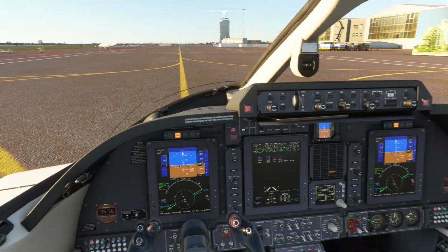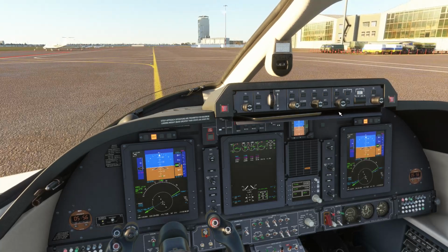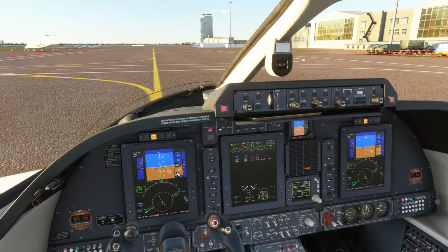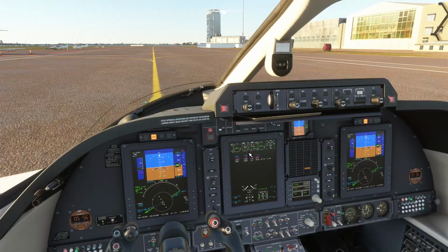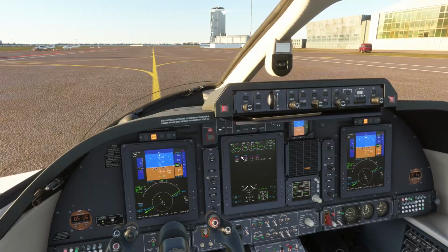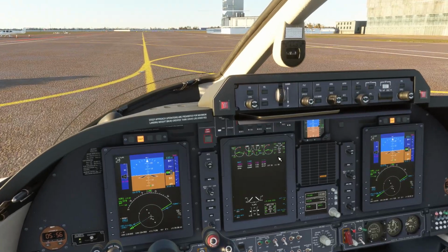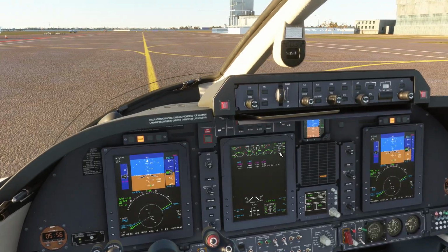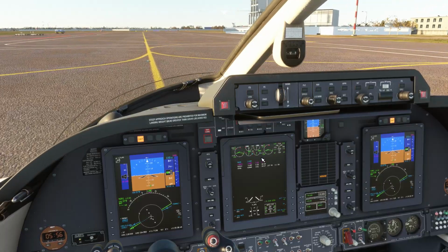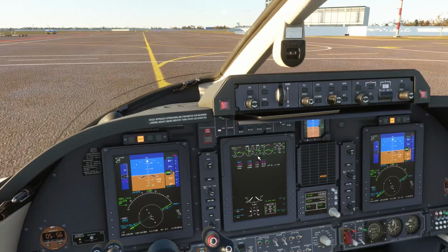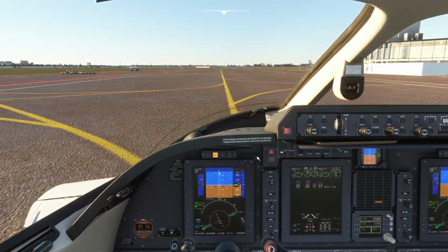Flight instruments, going further through the checklist. So legally we should go from the beginning. So brakes we checked, flaps are synchronous, steering system is taxi, prop reverse we checked, flight and engine instruments. So everything is fine here. We have ITT below 1100, oil temperature below 110, we have pressure at least 60. We have our fuel here, we have NGs at least 54 bilaterally, which is exactly what we want.